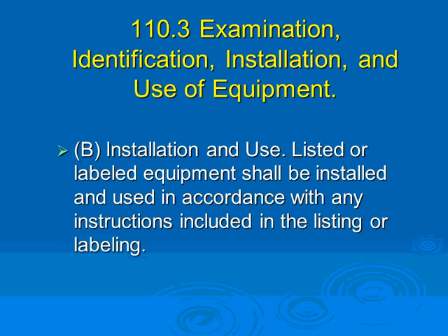Listing, if you look at the listing of the GFCI, it has to be exercised monthly, right? So now, by interpretation, some inspector will come. If it has to be tested monthly, how are you going to move this plasma TV or this big vending machine to test that device, right? It's not accessible. So that's why they catch you a lot on equipment, though the code doesn't say certain things, but based on listing and labeling, installing certain equipment based on the NEC code might violate the listing and labeling for them.